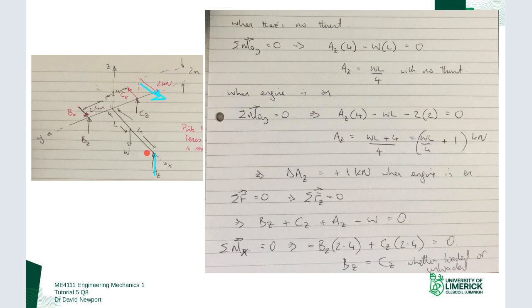So that causes the reaction component at A to change. Once that changes, then the loads in the other two change also. So just because you introduce this force coming in this x direction, you cannot assume that the vertical reaction components stay the same. So always be very, very conscious of that. When the loading condition changes, the reaction forces likely change. So don't assume that they are the same, assume that they change.